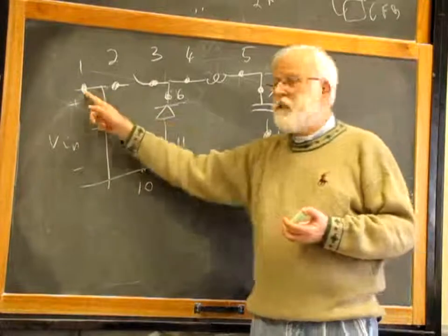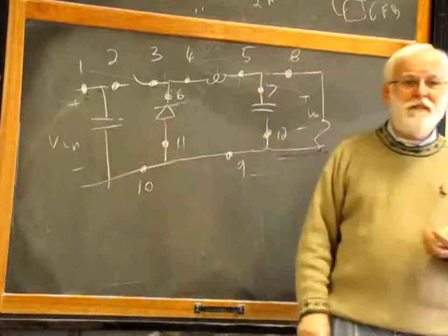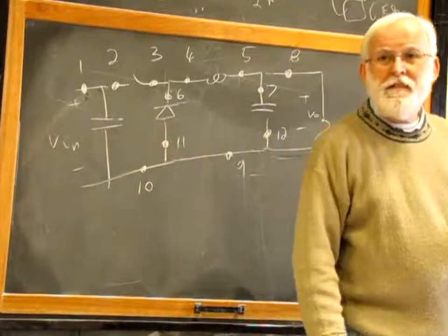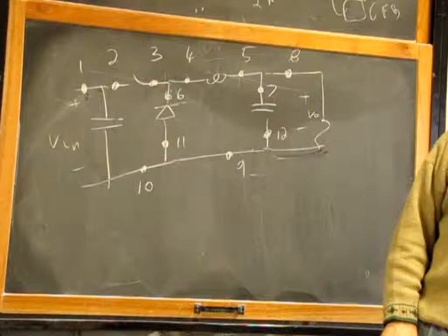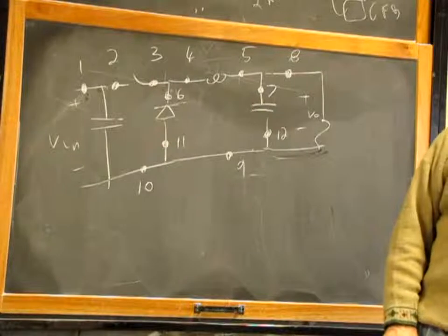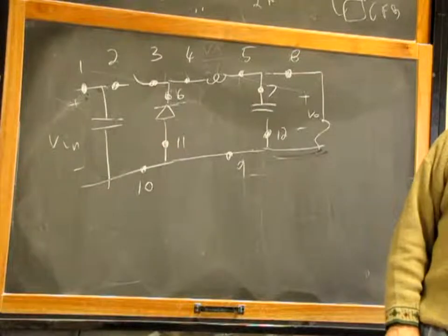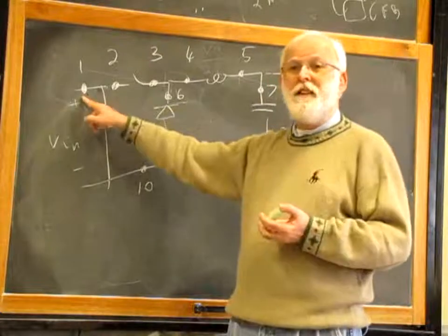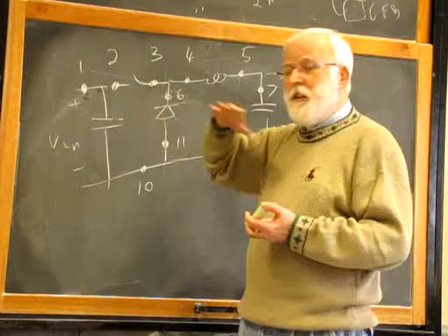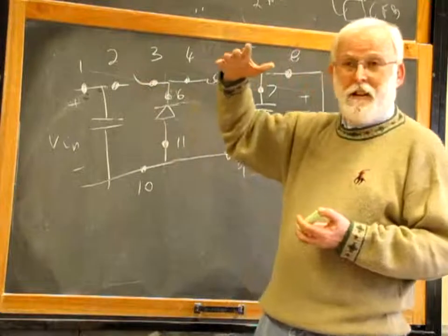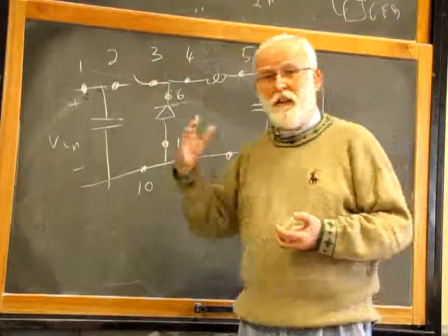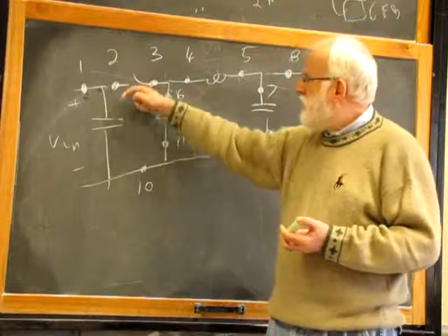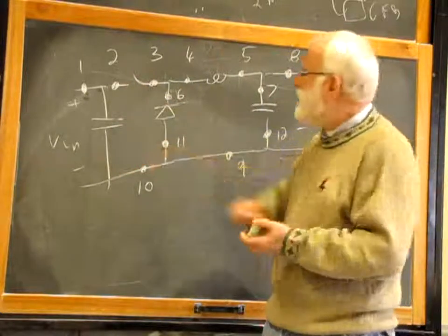Do I see the peak current if I measure the current over here? No, why not? Because over here there is just a DC current going in. All the ripple that is carrying the information on peak value is just passing to the input capacitor. So this is a no.